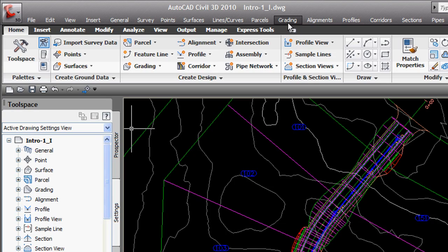If you do have some real customized pull-down menus, what I would recommend is that you go into the CUI, edit the menu bar so that you take out all the generic commands and just put in your customized ones if you want to do it that way. But I think if you start working with the ribbon, you'll find that that's not as necessary. With the quick access toolbar, you could just go ahead and put a few often used commands or a few customized commands up in there.